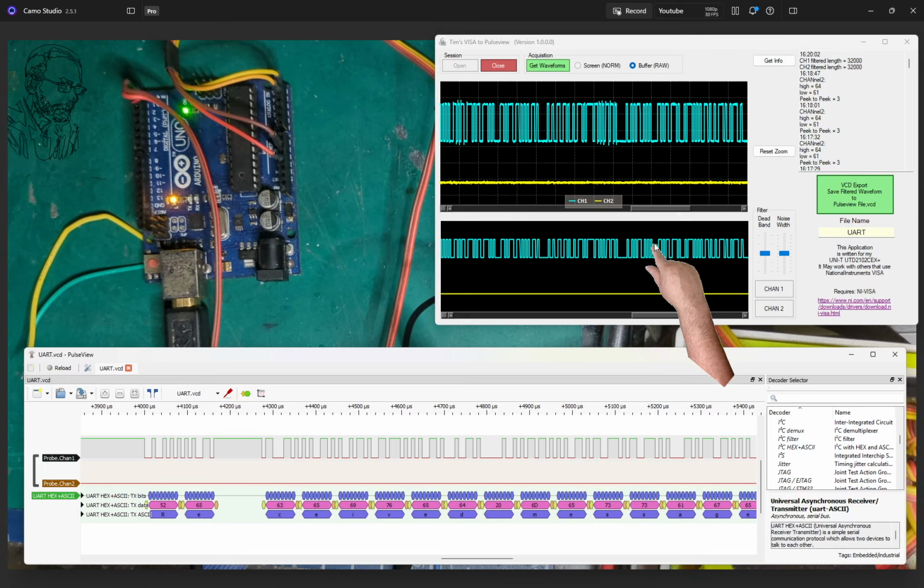But for actually converting them, you'd use a digital analyzer. But to save me digging out my digital analyzer when I'm just probing two serial lines, I find connecting this up is a lot easier and quicker, and I can still keep messing around with my probes and my oscilloscope. I've only got the one machine connected up.